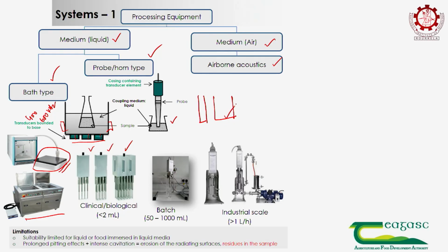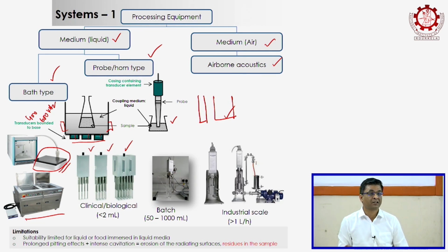Sir, I have seen a single probe, but different size, different length. Different size and length means they deliver different amplitude levels. In order to know the amplitude level, you have to go to the manufacturers. They only can tell you what is the amplitude of that machine. Measurement can be done, but you need precise tools to do the micrometer measurement. So, different diameter dictates how intense you are delivering the ultrasonics. That is important here.